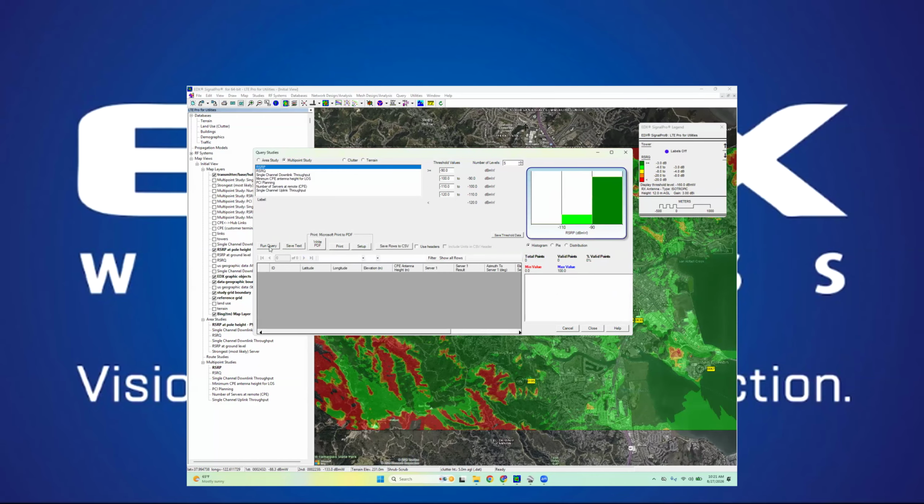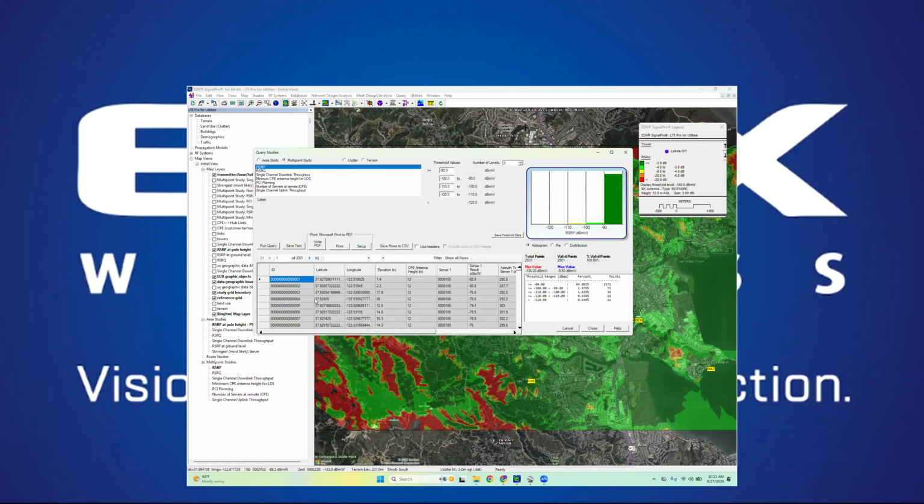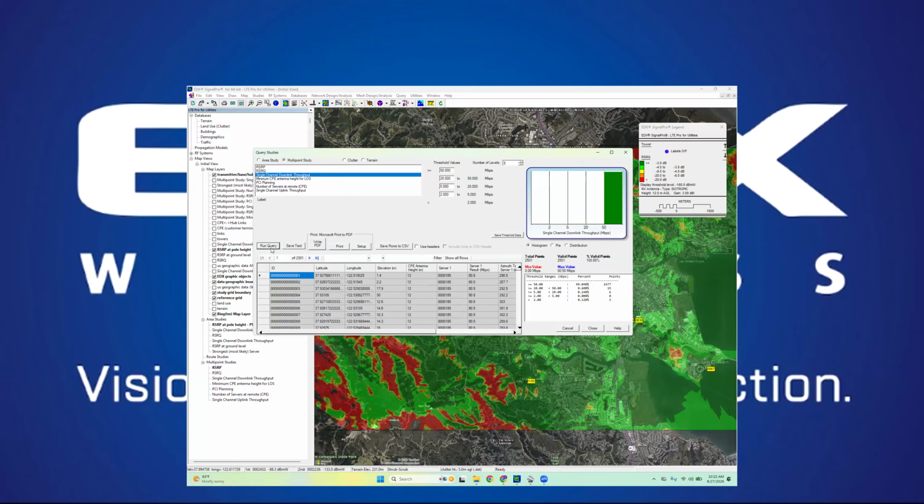If I run this on a multi-point study, so let's say I run the query for my fixed point to multi-point subscribers, then I've got 2,501 of them here, and each one of these is then a fixed subscriber, and it's showing me my calculated study result, just depends what study I've queried here, as well as the azimuth, elevation, and distance back to the serving sector that's providing that coverage. And if I want to do this for throughput, then of course I can do this for throughput. The only difference I'll see is that I'm getting my answer in megabits per second.